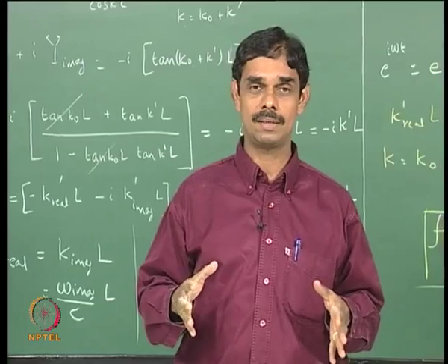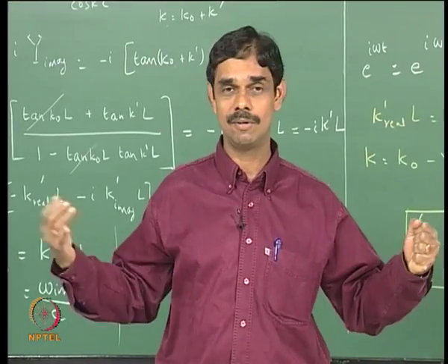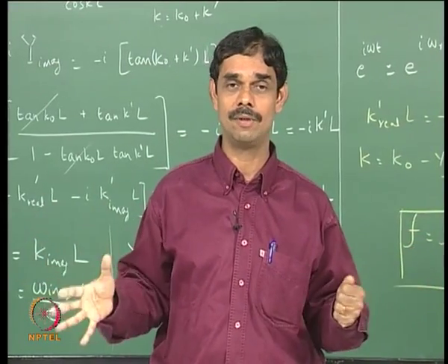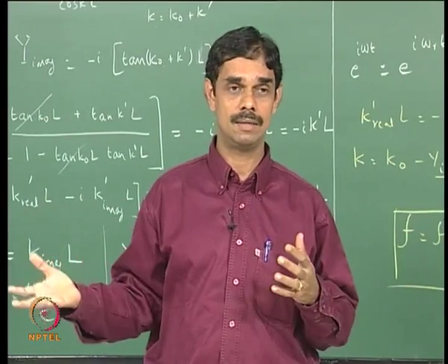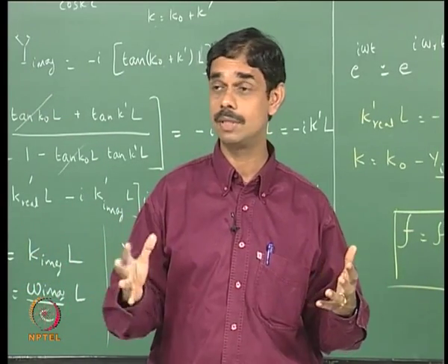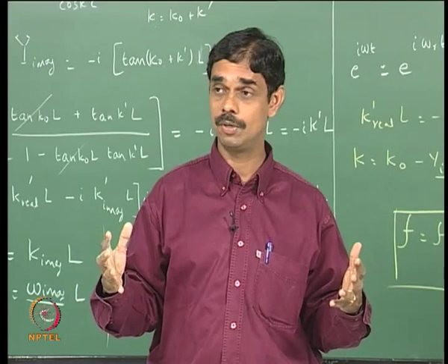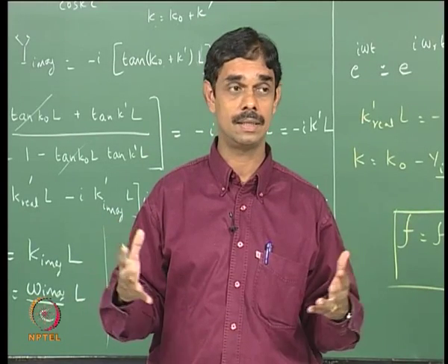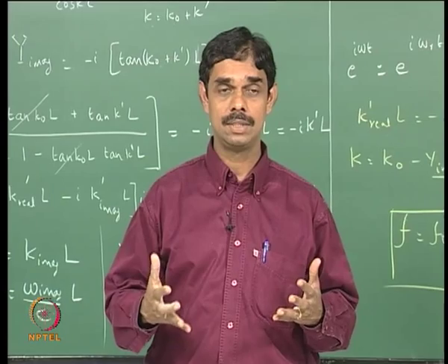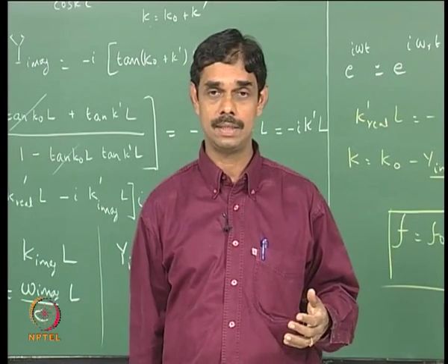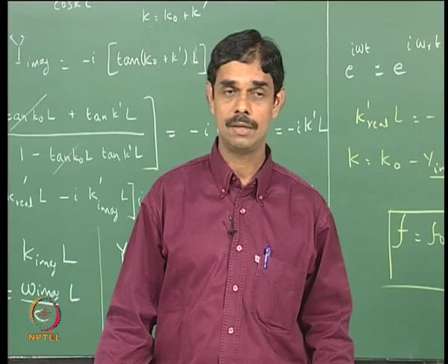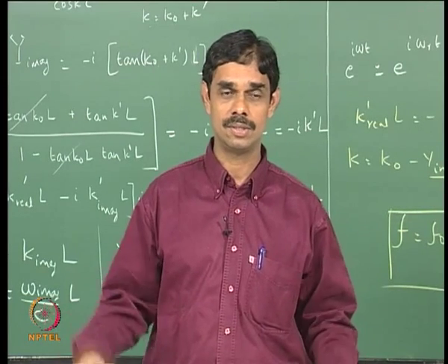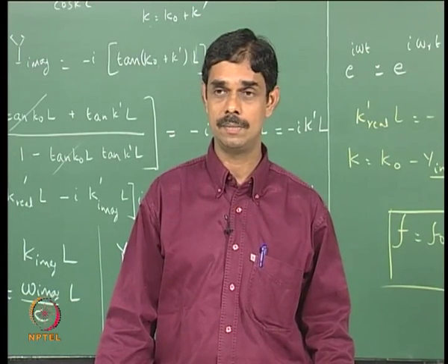And if it is like one particle in the sound wave, it probably does not matter, you can think of it as one way coupling, but if there are a very large number of particles, the sound wave or the acoustic field will start losing some amount of energy, so it is like now a two-way transfer. So this would lead to acoustic attenuation, and that is what the solid propellant motor designers try to make use of as some kind of insurance or protection against combustion instability.